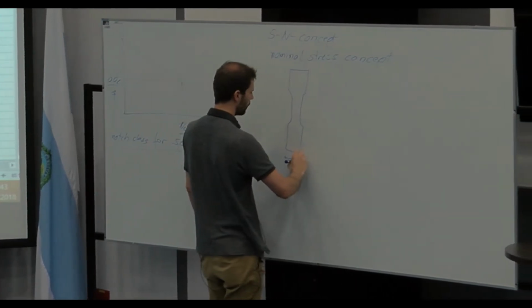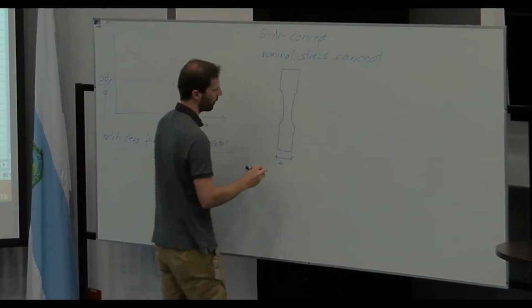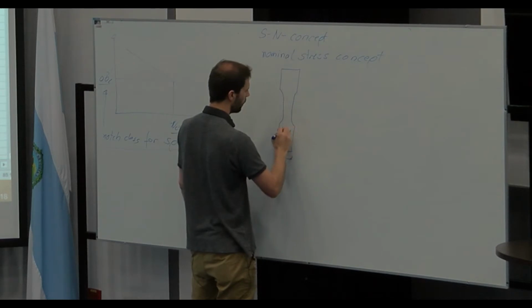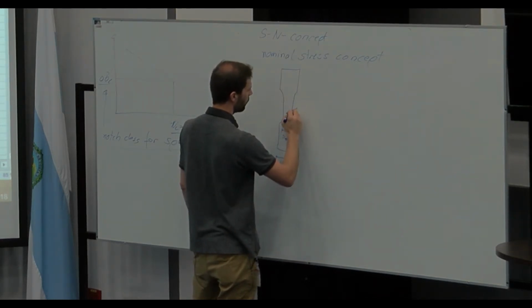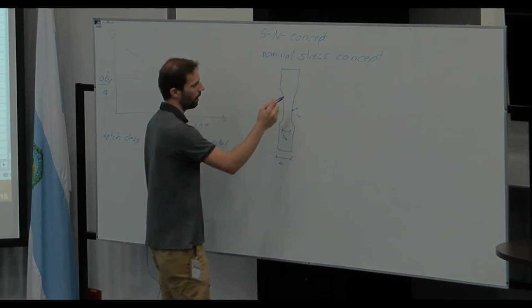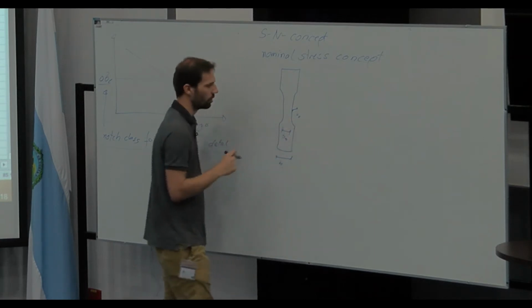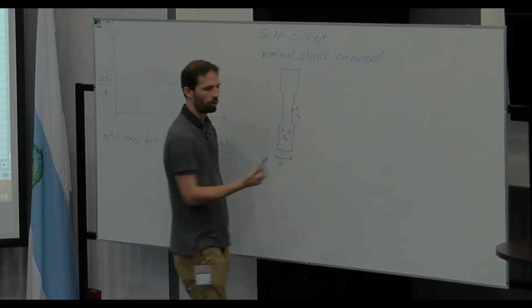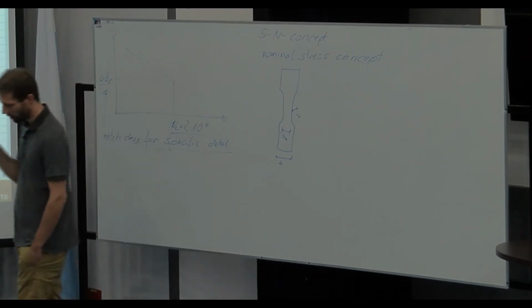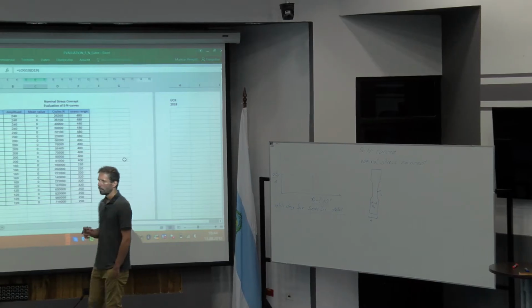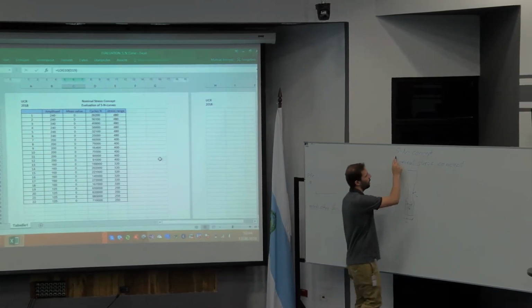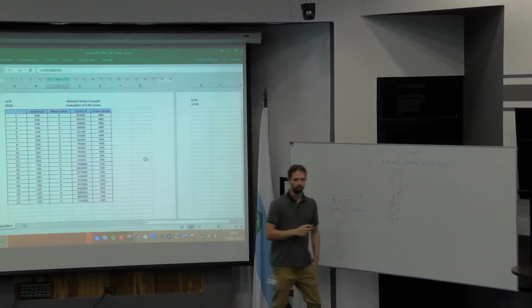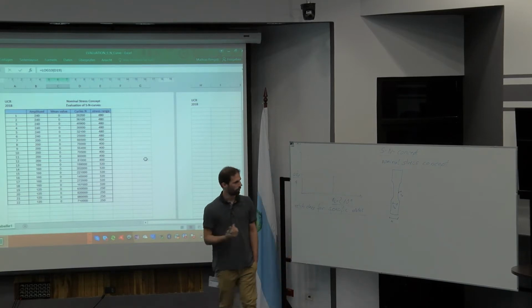We have here the B at the clamping, we have here the B0, and of course a width or a depth, which is the A0, and at the end some different definitions about the curvature for specific material testing. But if you just go for some basic curves in our SN curve, we can also use the tension test bars.